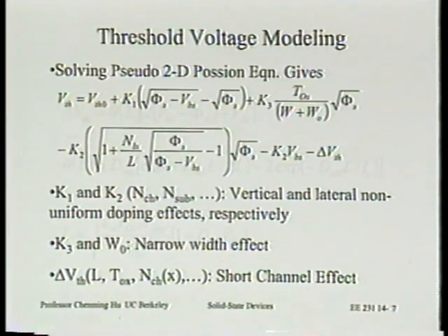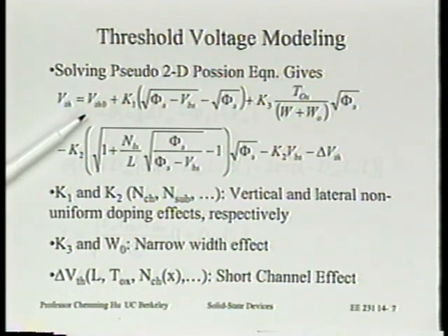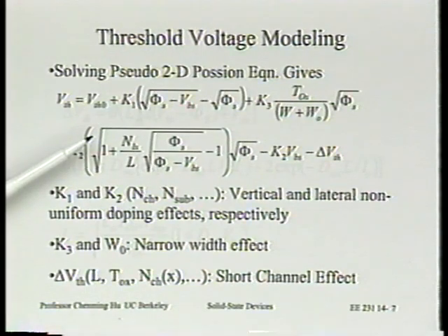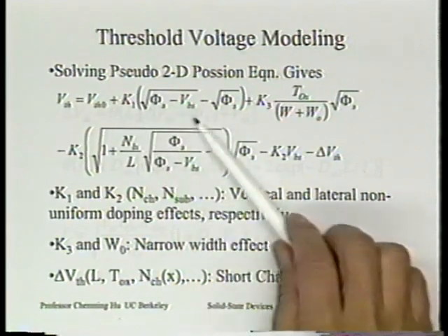Okay, all right. So specifically, if you look at the equation used in BSIM, how does BSIM describe VT? You start with a quantity called VT0. That will be the basic VT model, maybe for a long channel transistor, you know, a simple model. This is something that BSIM will not be able to predict because it depends on doping profile, doping density. So this will be what we call a fitting parameter. All right? We'll have to determine that from measurements. Yes, right? Okay.